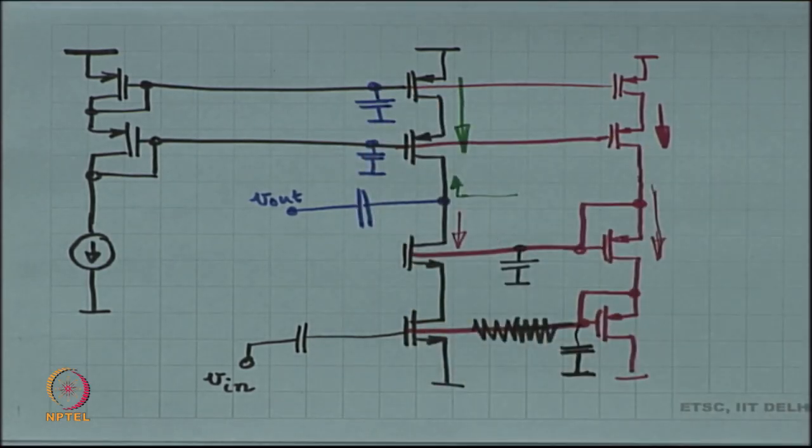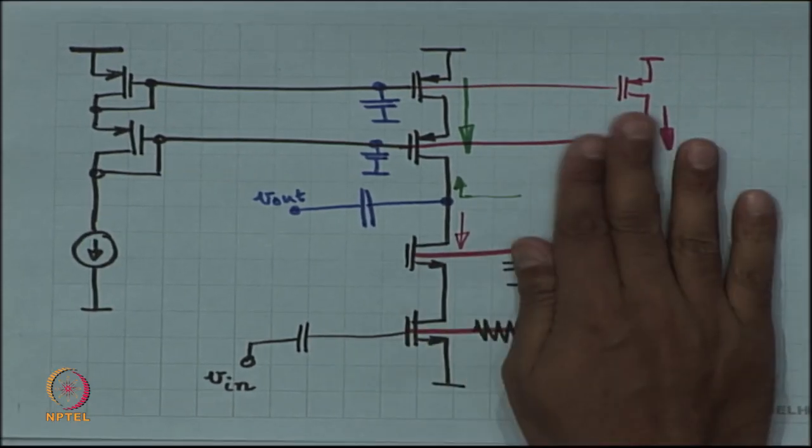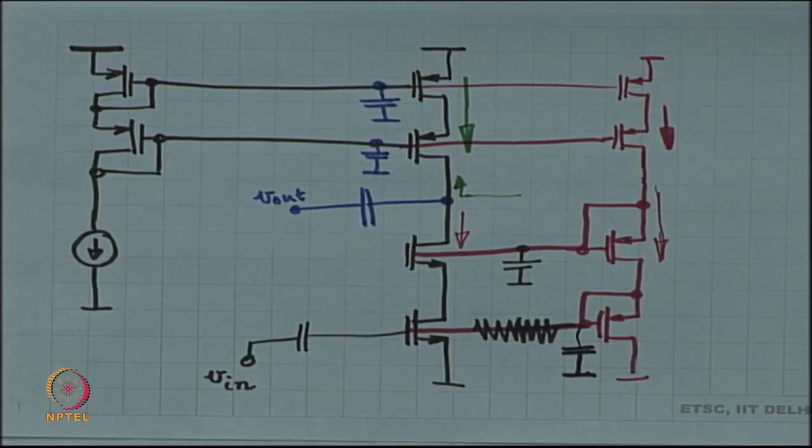Okay. So, all the gates, they do not move, fine. This is basically the idea behind this circuit. So, you have all these coupling and decoupling capacitors, and you need to isolate the bias from the signal. Fine, this is the cascode amplifier, and this is biased using current mirrors.